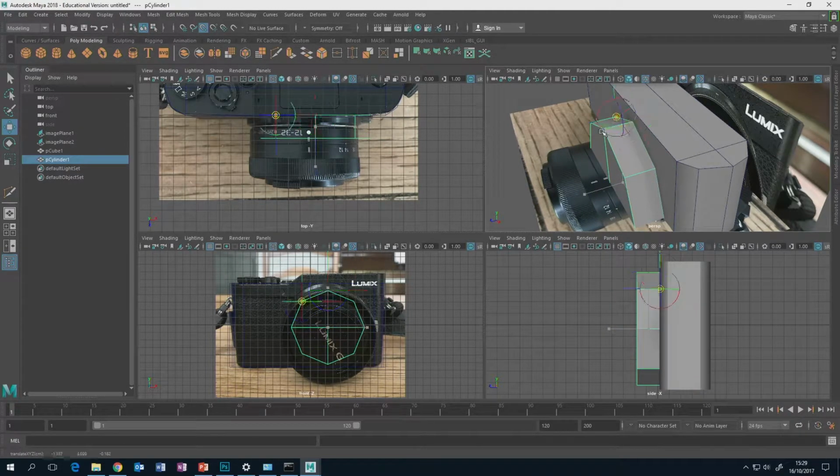So I'm going to move it around, and you can see it's snapping to these points, which is extremely useful for when we want to scale from the base of an object or the side of an object. So I'm going to move it to just here. Holding V, moving this around, let go. Quite important to remember that I've got to press Insert again to get myself out of pivot mode. Now when I scale, I'm going to be scaling from that base just here, which is a lot more useful. Now I can scale out.